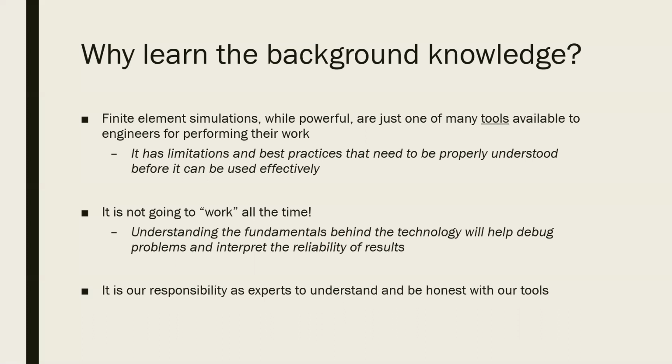And so the second point I want to make is that even when you set it up properly, and you understand it well, finite elements is not going to be effective for every single problem. So it's not going to work all the time. And so, by understanding the fundamentals behind the technology, it will help you either debug some issues, or simply say that this is too difficult of a problem, or this problem is just not suited for finite elements. That's really important for you to know as well.